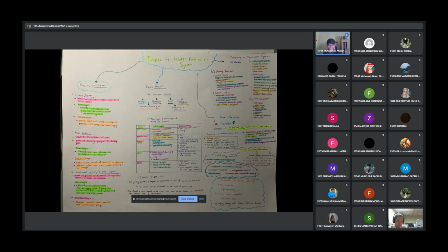Non-revenue water. The definition of non-revenue water is water that has been produced and is lost before it reaches the customer. Leakage measurement procedure: the first one is indirect leakage measurement and the second is direct leakage measurement. It has 4 methods to control the leakage.